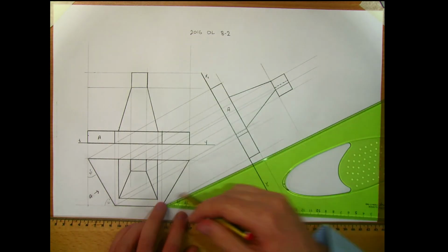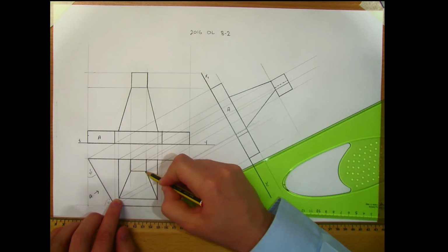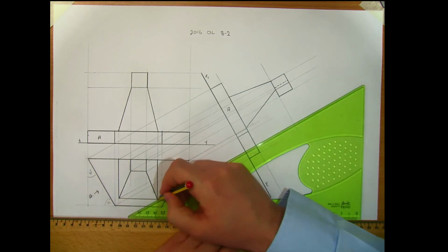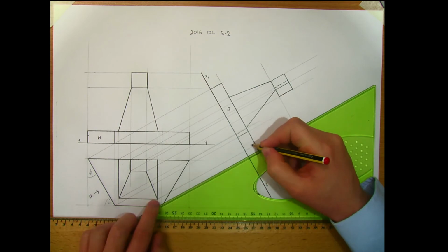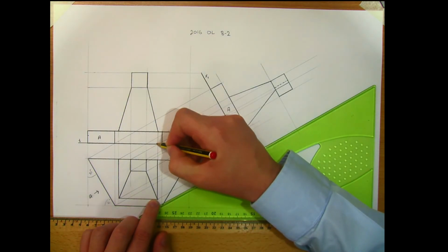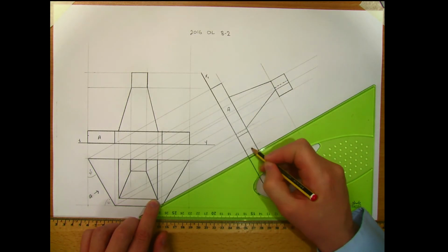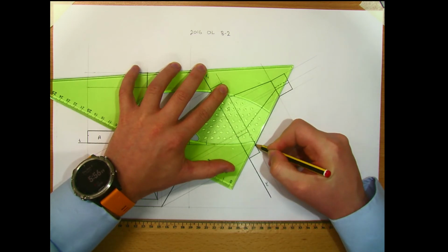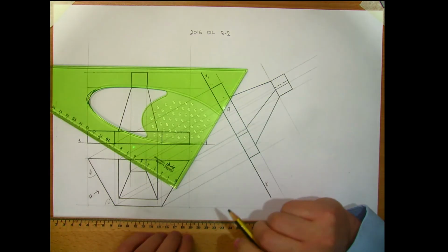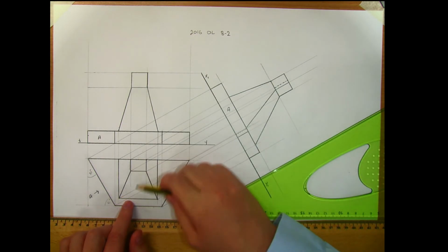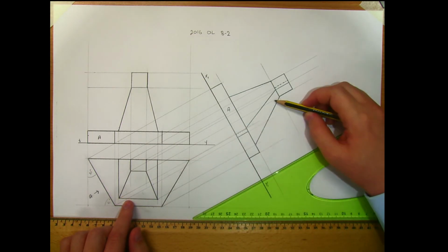So again, we have this corner, and this corner of it. Now we're just looking for this one down here. So taking this point, projecting up along, that's this point, follow it up along, it's that height, 15 millimeters off the XY line. It's the same height up here, so we can join these two up. And that gives me the next point up there. Okay, so all of this area here is this area here.